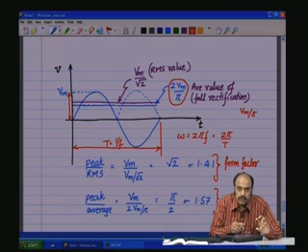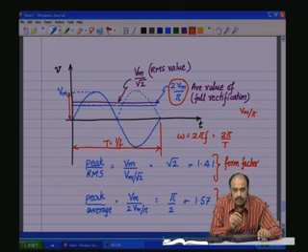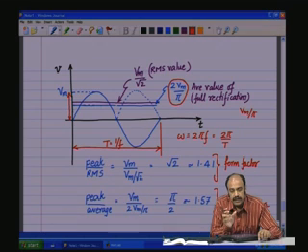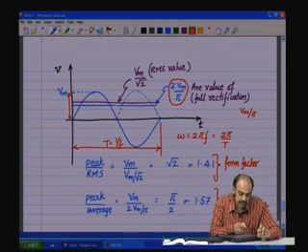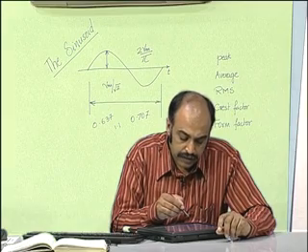So, it is V RMS square by R, or it is I RMS square into R. In fact, in the wall socket ratings, what you see, the 230 volt rated, the rated voltage or the rated amps, 5 amps or 6 amps or even 15 amps socket, the amps that relates there is the RMS quantity, not the peak value or the average value. So, what is mentioned in all the wall sockets and all the power rating or the nameplate ratings are generally the RMS quantities, because they relate to the power. So, the RMS values are pretty important there.